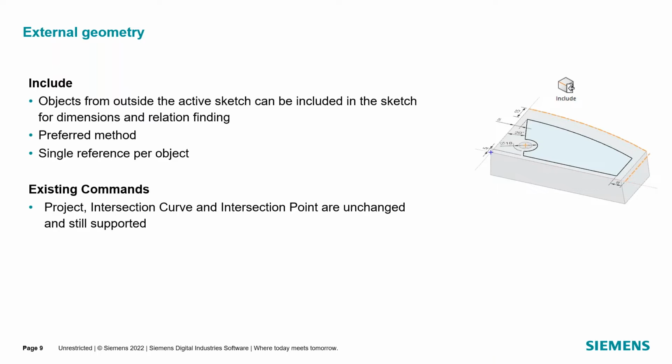As you see there, you get a dashed line. And by being a reference, it will not participate in revolves and extrudes and other things you traditionally do with a sketch. You can, on the fly, pick those edges. By default, the selection intent for a sketch is select to current sketch only, because especially with newer users, sometimes you would be picking stuff and you'd pick stuff three or four levels deep, an edge in the background that you really don't want. It makes it very hard to debug your sketch and do other things.